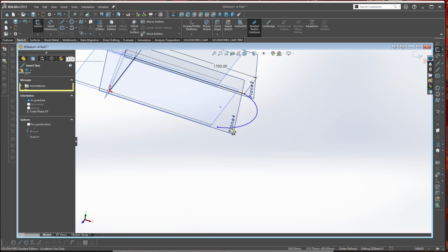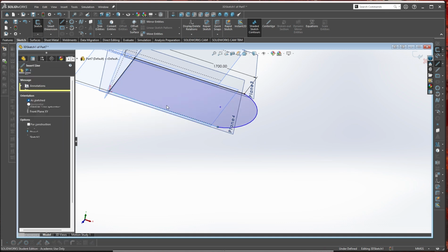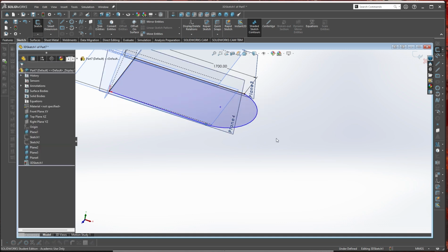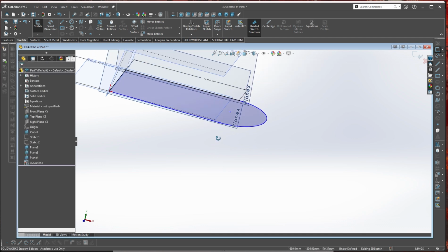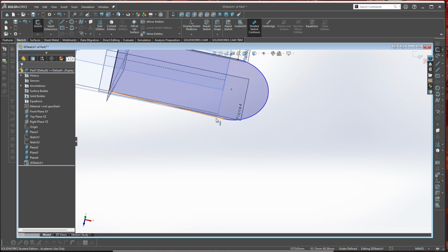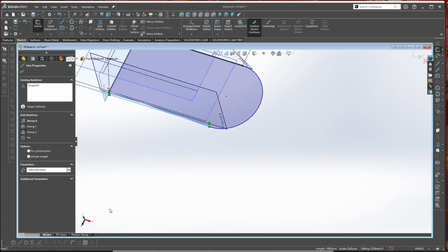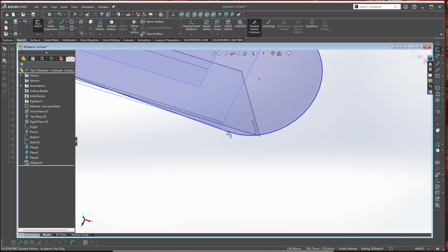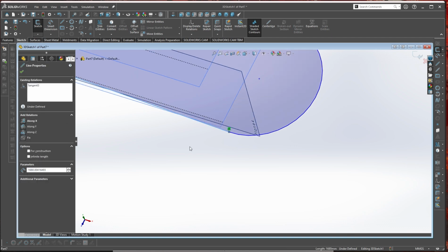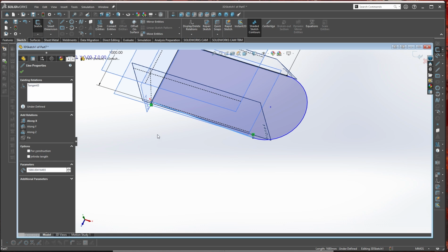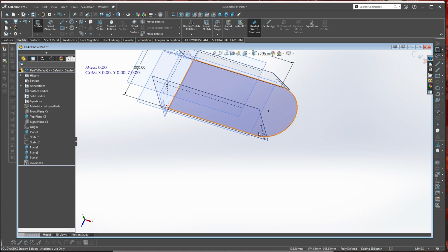Something like that. Last but not least, let's drop our line right there for that to create our tangents. And this needs to be along X. So that line right there, it's similar to using horizontal, but remember in 3D Sketch we don't have horizontal vertical relationships. As you can see right there, we don't have those, but what we do have is this. We want this along the X. So as soon as we click that, notice everything shores up and we're fully defined at this point.